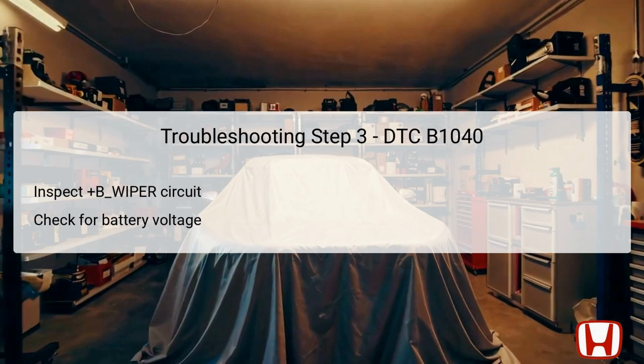If voltage is absent or significantly below this threshold, it suggests a failure in the power delivery system, necessitating further inspection of power distribution points. Ensuring that this fundamental power supply is intact is essential for the subsequent functionality of the entire system, as all operations depend on reliable electrical energy.